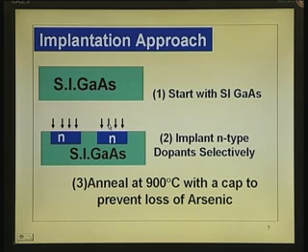The arrows show the regions, these two regions are the regions where you implant n-type impurities, maybe silicon. And when you do implantation, you have total control on the number of atoms that you are putting there. You can virtually count. You count by measuring the current. When you implant, there is a beam current.